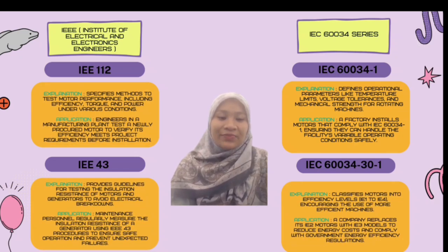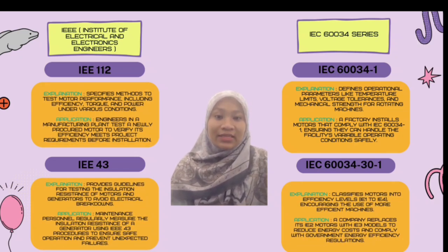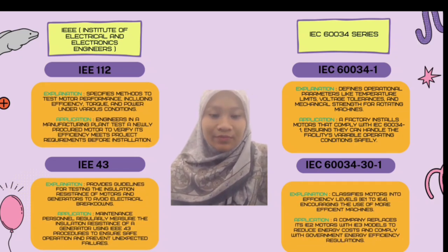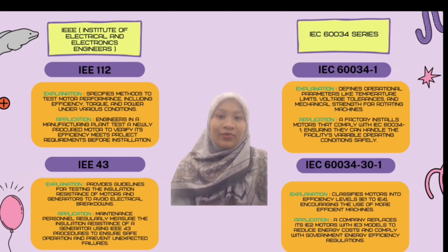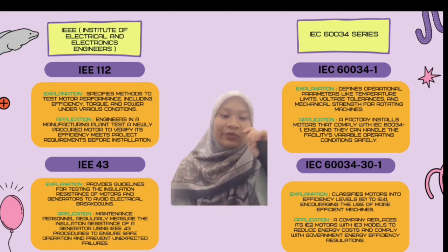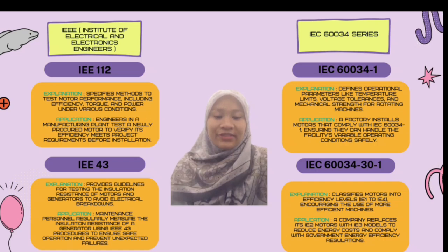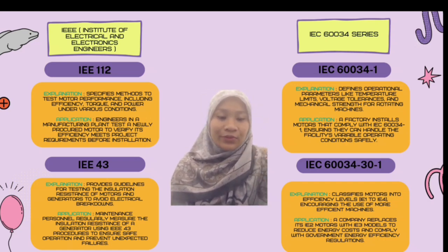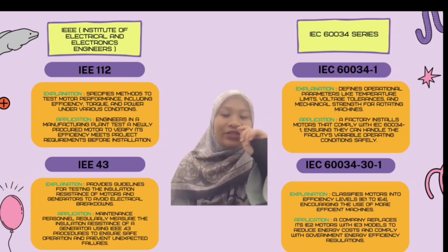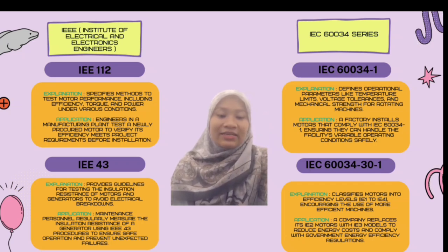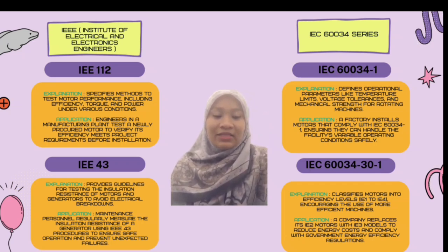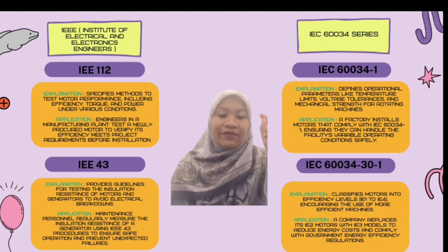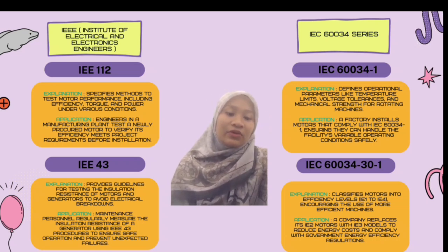I will explain two examples for each standard. For IEEE, the first is IEEE 112, Standard Test Procedure for Polyphase Induction Motors and Generators. It specifies methods to test motor performance including efficiency, torque and power under various conditions. The application is an engineer in a manufacturing plant tests a newly produced motor to verify its efficiency meets project requirements